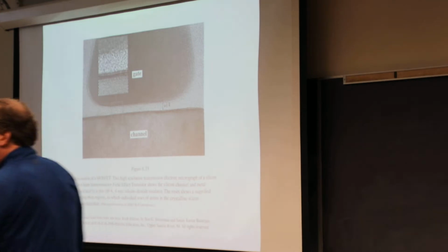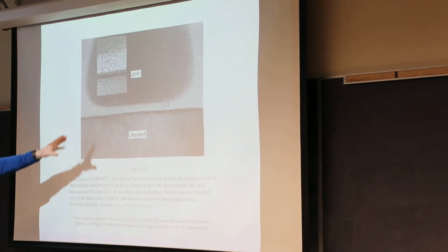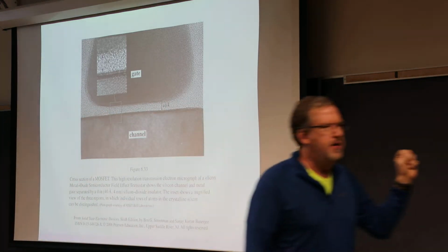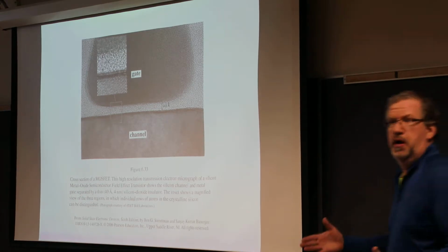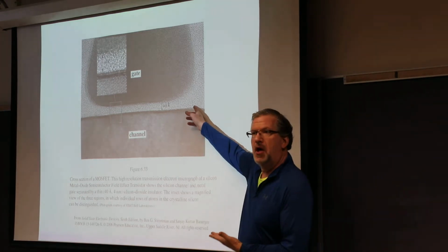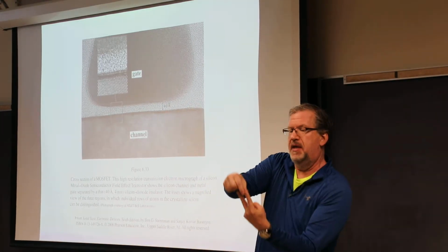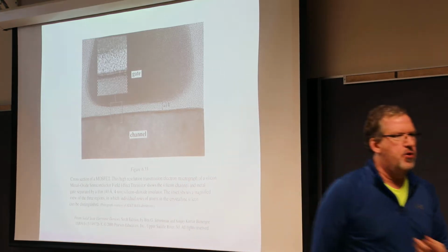The lowest planar density. Boom. Lowest plane of density. Therefore, all those dangling bonds, which we'll get into later with the transistors, will be fewer, right? Because there's some that are stuck in that SiO mode, because it's a two-step process to go from silicon to SiO to SiO2. So some of them are trapped.